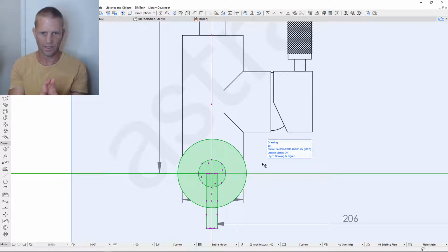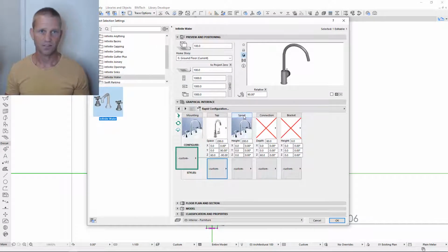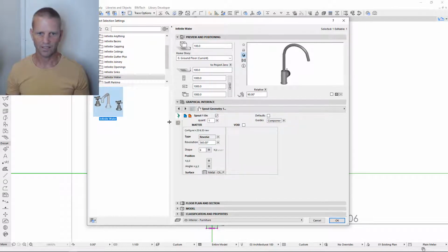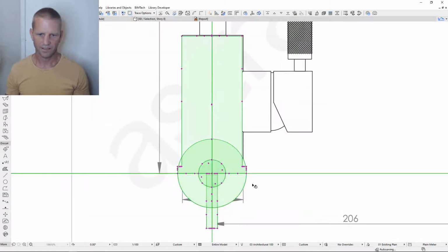At the moment you're looking at a stood up revolve, when you need to look at it side on if you want to edit it. So we go into the element and we find out where that revolve is. It's part of the spout. So we click on that and we have a look. Spout geometry 1 is a revolve, so that'll be it. The second geometry will be the tube, which is that path that we just set for the spout. Okay, so let's go back to geometry number 1. This will be rotated minus 90, yep. So let's send that back to 0, click OK, and now we have access to the actual element.